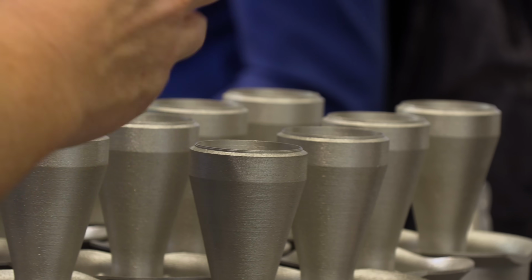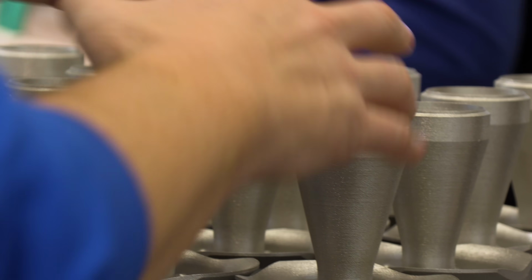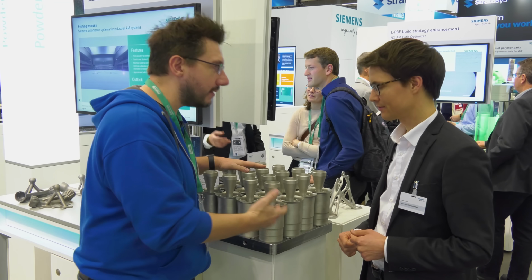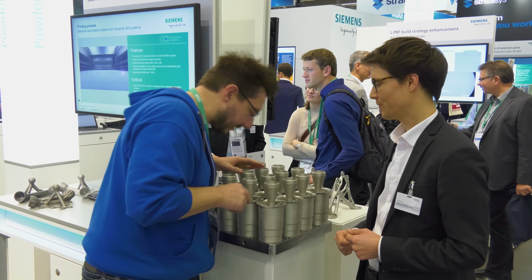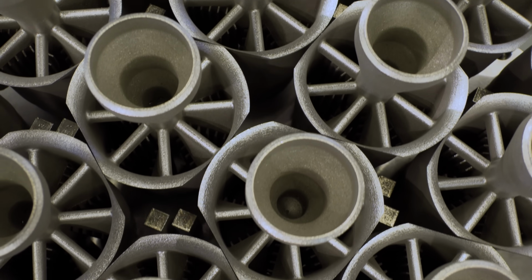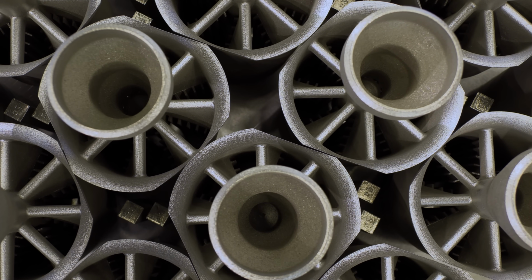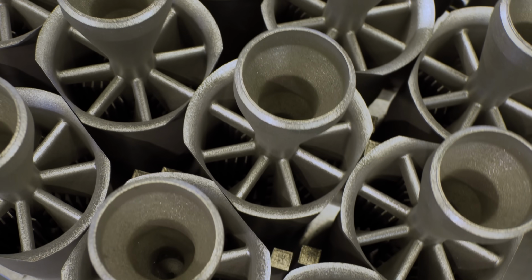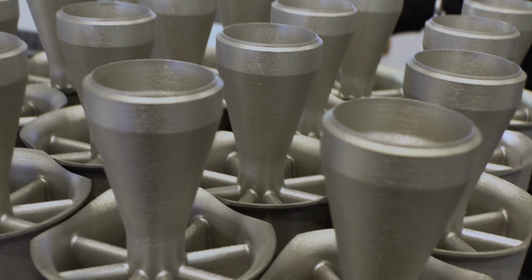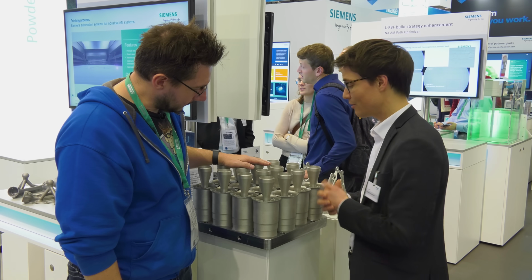Well, and it makes sense that you're having to do many of these, and so you have to take advantage of all of the build space, and you can see the clearance between parts is very minimal. It's completely optimized to get the best output and the best yield and optimize the build space, in this case 400 by 400 millimeters in XY direction, and put as many products in and really have the best utilization of the machine.